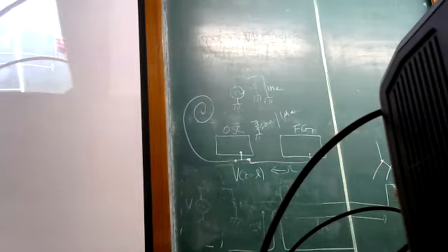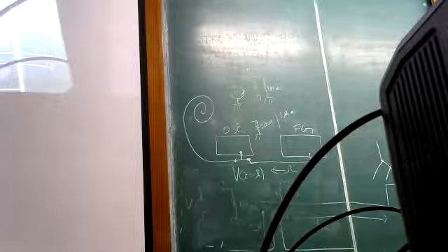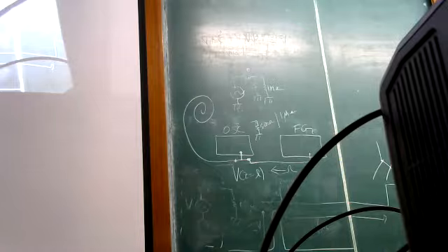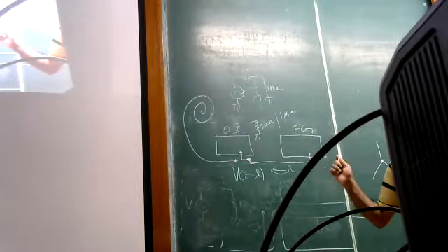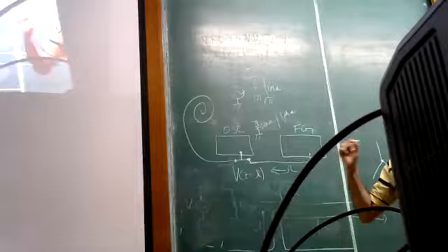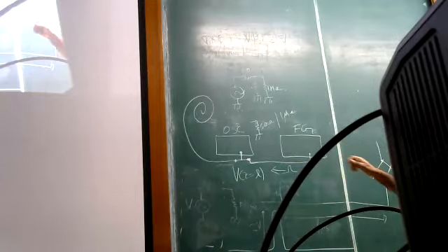Can a voltage source have infinite input impedance? An ideal voltmeter has infinite input impedance. An ideal voltage source has zero input impedance. But this is a 50 ohm system.